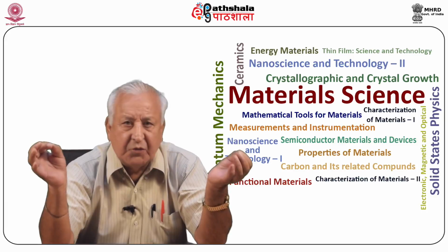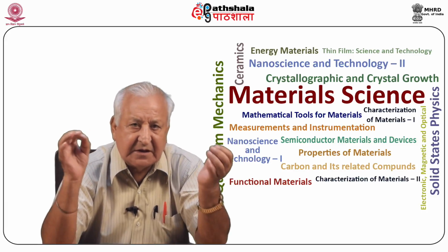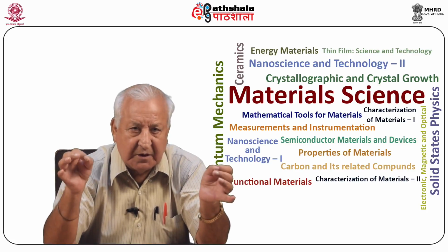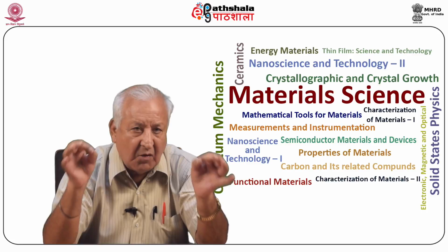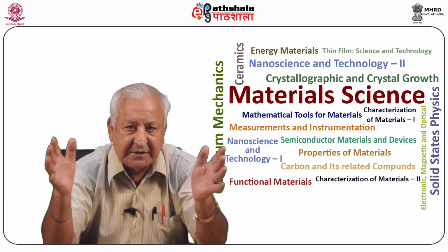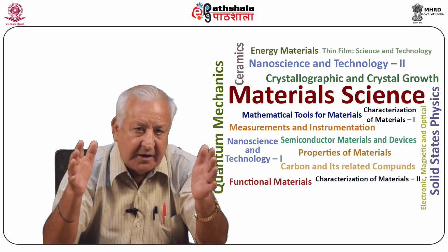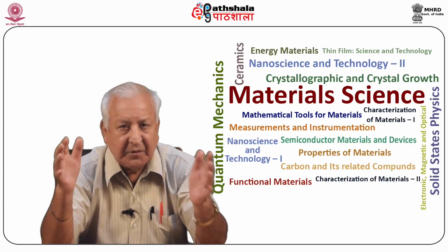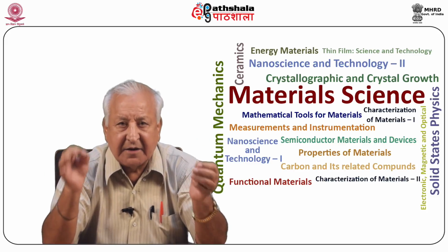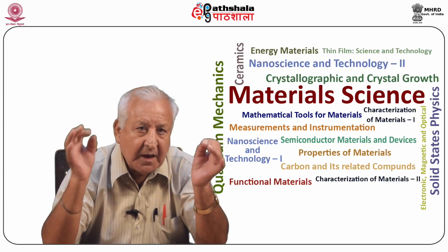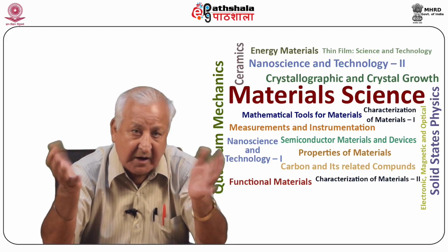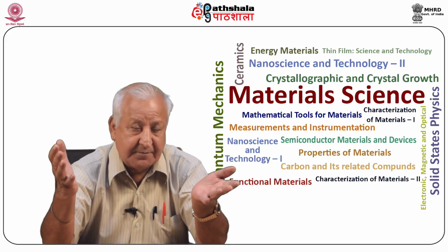The composition is homogenized by vigorously mixing the same. The well-mixed composition is pressed into a platinum crucible and placed in the furnace, where it is held at a temperature of approximately 1300 degrees centigrade for a soaking period of 12 to 16 hours. It is then cooled at the rate of 2 degrees centigrade per hour till 800 degrees centigrade is reached. Thereafter, it is cooled at the rate of around 100 degrees centigrade per hour till room temperature.